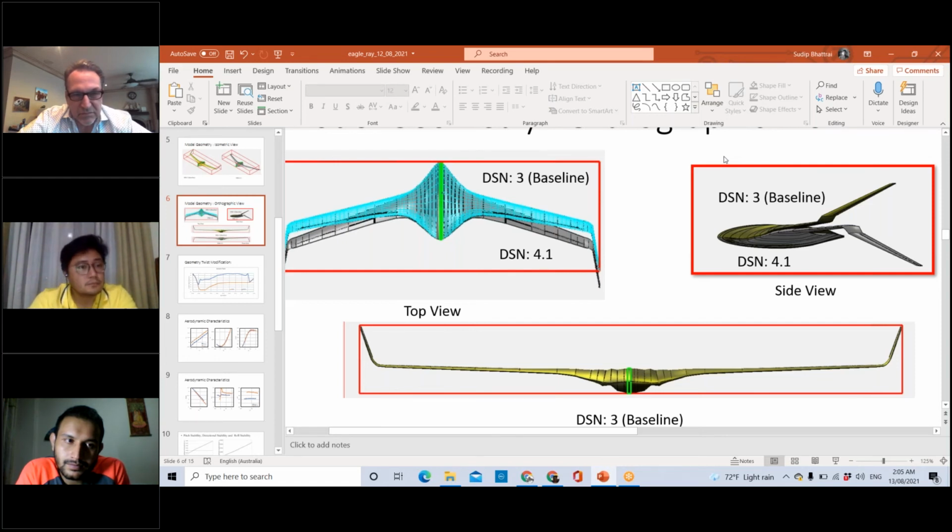Yes, so when we were just starting to fly baseline 3, I was not yet sure about how I was going to do the takeoff, and in X-Plane there's this feature where you can take your airplane up in the air directly, starting from a particular altitude and speed. And it was very surprising because whatever speed and altitude I would give, it would never stay in that position. It would immediately dive, or in some positions it would immediately pitch up and stall. We thought that was maybe partly because when we are flying, we are always at a high angle of attack, and stall is very nearby.